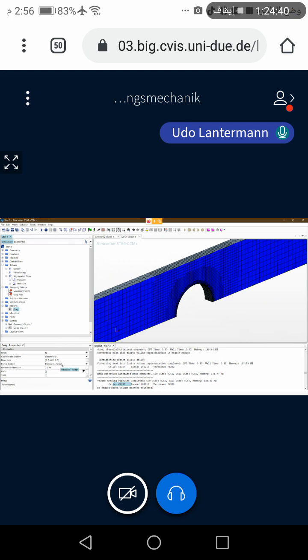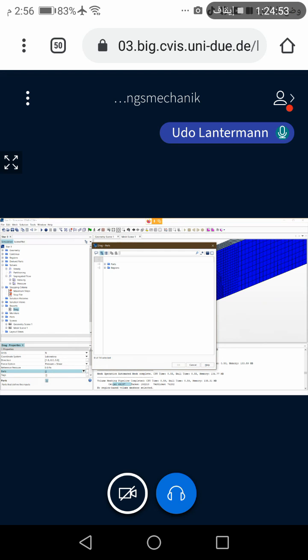So in our case we also use pressure and shear here. The only one we have to choose is the part. That means we have to choose the patch on which the drag is created, and this will be our cylinder.